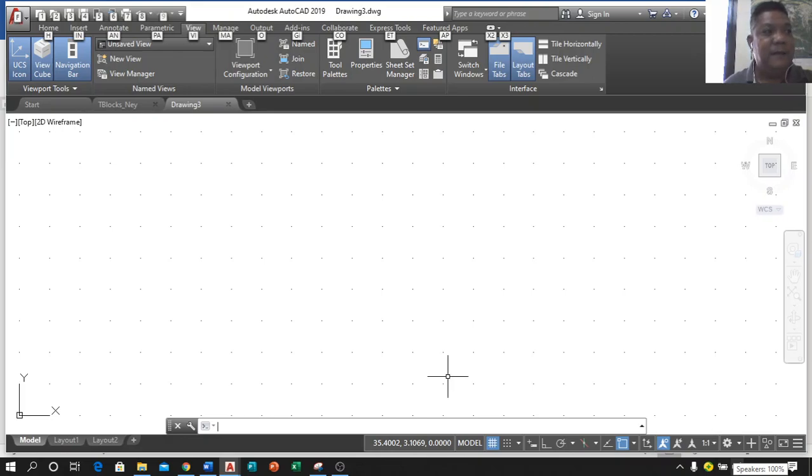Creating a simple plan. In this set of tutorials, you will learn how to draw your very first set of architectural plans. You will get started by working on the floor plan of a simple studio. You will begin with the exterior and interior walls in our plans. You will learn a few tools and tips that will help you quickly and efficiently draw walls that will define each space throughout the plan. Next, you will learn how to quickly draw the doors and windows that will populate your floor plan.